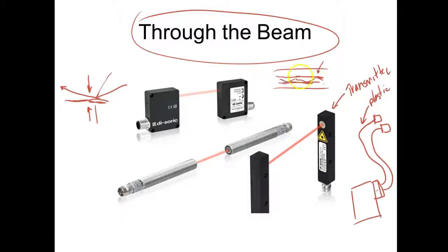If we exceed the angle, then what will happen is it'll escape through the cladding. That makes sense? And of course, what advantage does fiber have in an industrial application? We're not really concerned with speed. What we're concerned with is magnetic interference. We call it EMI. So one big advantage of fiber cables is they're immune to interference.